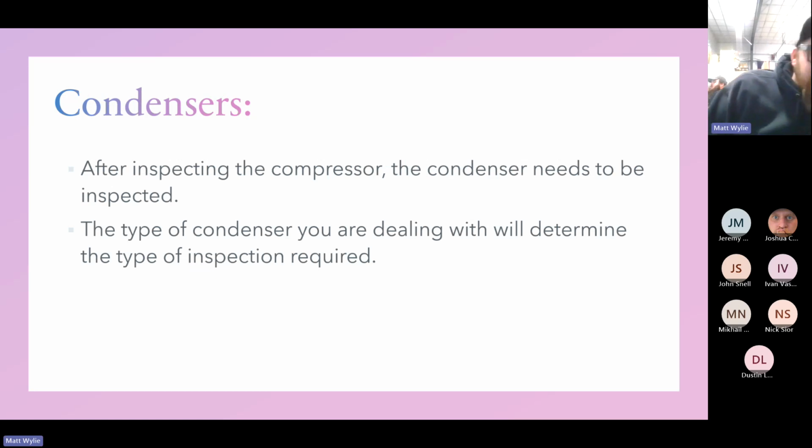So, condensers. After inspecting the compressor, the condenser needs to be inspected. Determine the type of condensers you're dealing with to determine the type of inspection required. So with condensers, you have the microchannel condensers, which get clogged way easy.